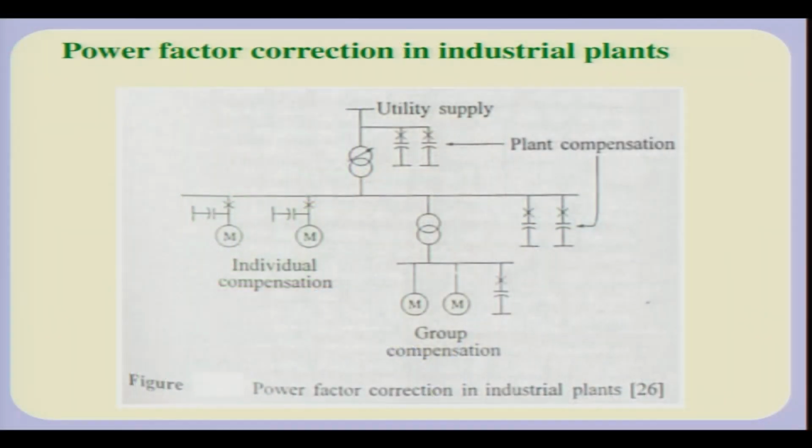I mentioned some time back that you may wish to connect compensating devices. Here I have shown compensating capacitors, which may cancel any reactive power. For example, if you have a load which is inductive, which is drawing reactive power, you can compensate for that by connecting devices in which the current leads the voltage.